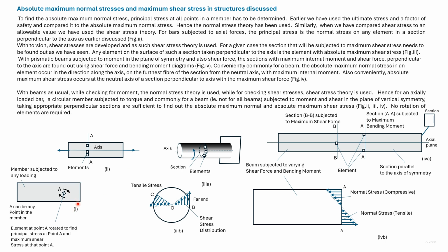The same exercise can be carried out for all the points in this member. We can then find the absolute maximum shear stress acting on this member. According to shear stress theory, such absolute maximum shear stress needs to be less than an allowable shear stress for the member to be safe.